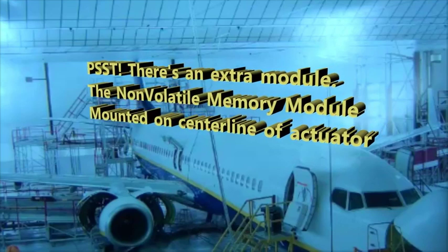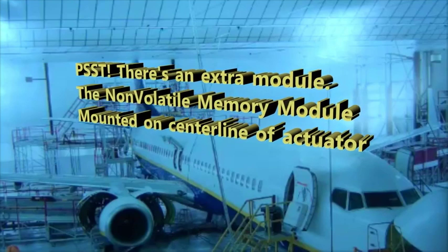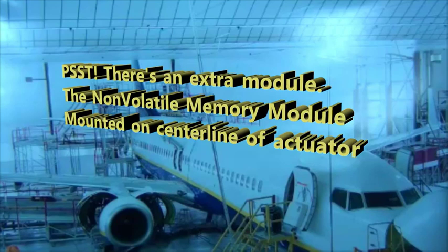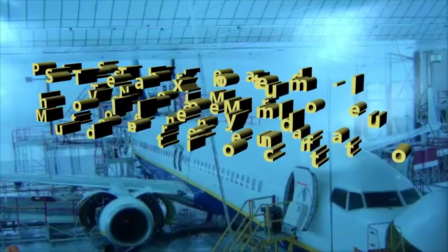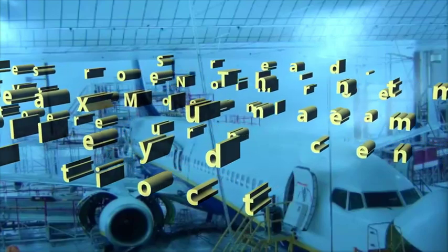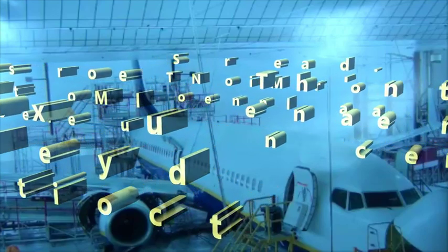And what is it doing? Why is it even there? Well, this is going to contain values and also the calibration points that are going to be used by the electronic module. It's also containing just basic vital information of the actuator: your part number, functional item number, and also the serial number of the actuator. So it's pretty cool, actually. It's an amazing little machine to do all that.